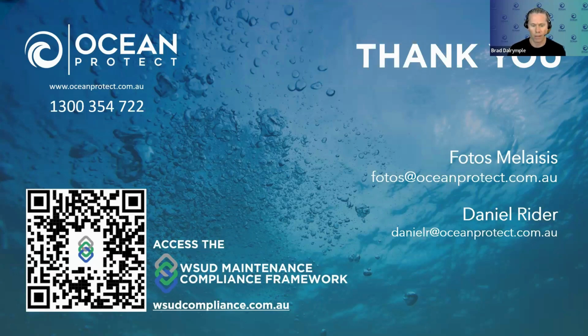Question from Matthew Funnel, and Matthew's from Scenic Rim Regional Council. So greetings, Matthew, the wonders of modern technology bring us all together from Adelaide to Parramatta to Hobart to the Scenic Rim. Matthew asks, are the standard maintenance periods of 12 months reasonable for all WSUD assets? I would say no. I think it's really dependent on the site. There's a whole range of characteristics that would be affecting how frequently these assets need to be maintained. I recognize for councils with limited budgets and capacity, maybe once a year is all that is possible. However, for these assets to work as intended, it would probably require a more frequent period than 12 months, in my opinion.